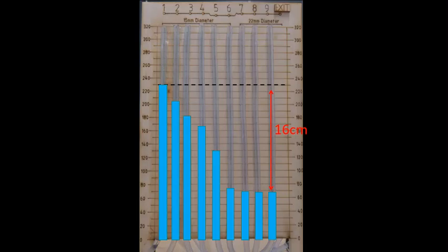This discrepancy is likely due to the use of approximate values combined with some additional head losses which occurred at the connections of the various sections. We also see the small 0.7 centimeter loss across the 22 mil section calculated is the reason why the final readings are also close together. Hopefully, this shows you all the useful tool in the ability to rapidly calculate approximate values of head loss for pipes of different geometries and compositions.